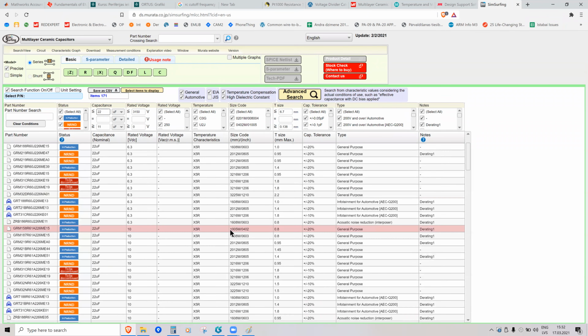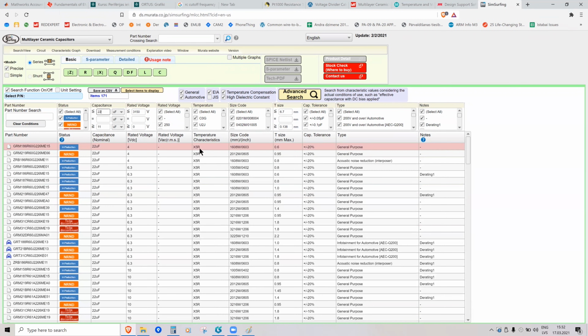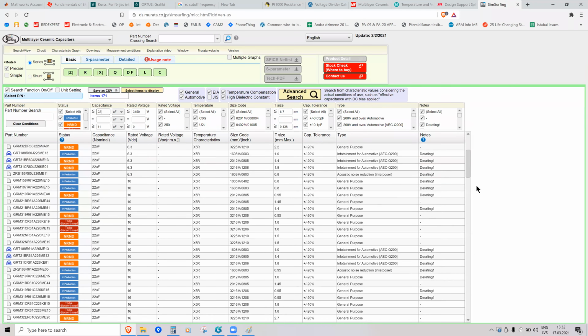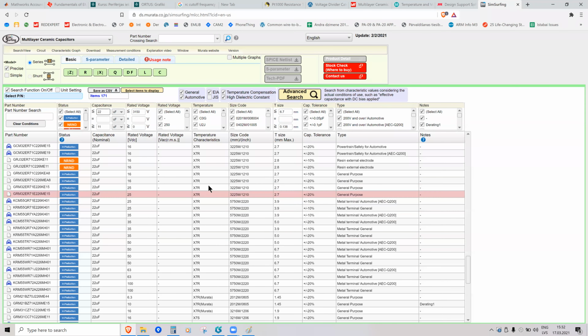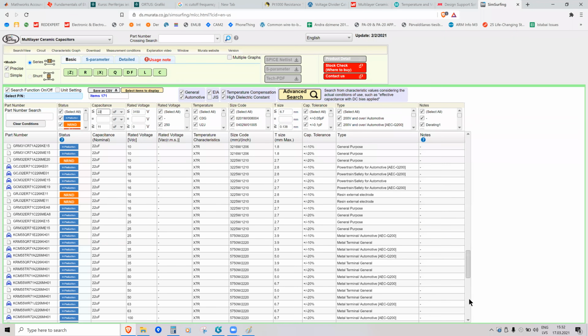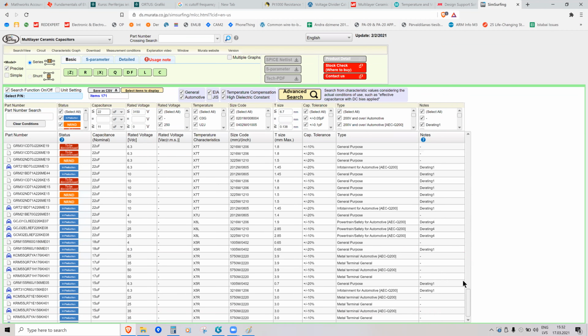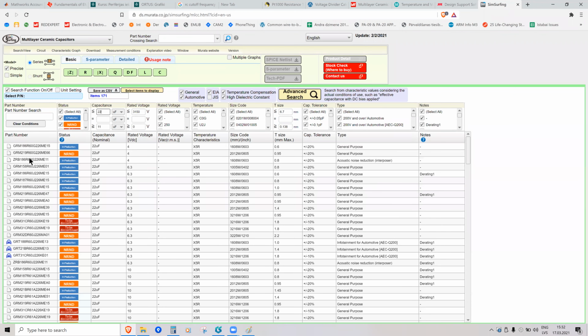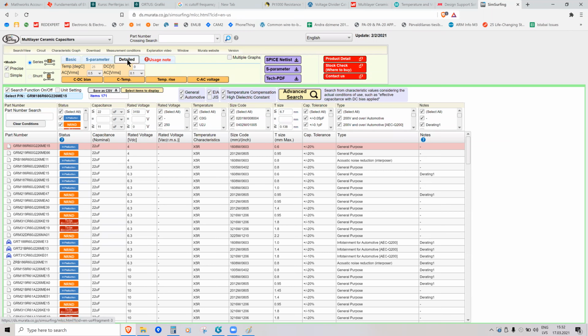As you can see, they have all kinds of capacitors. Their rating is X5R, the material type. They also have X7R and X6S, but I think X6S is very similar. All of them will have this property. Now it's slow. Okay, I'll select the first one here. I can go to capacitance versus, oh, here it is, DC bias.